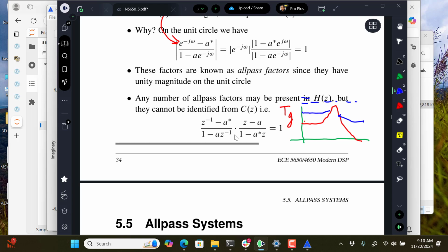Do I ever have to do this with digital filters? Not really, but I know that filters on SATCOM systems, which would be cavity-based microwave filters, have done things like this. They've been doing it for ages and ages. A cavity filter will be low loss, an efficient filter, but it won't have constant group delay, so they can equalize them in the design using cavity filter design techniques. But in DSP, you can also, of course, equalize things for group delay.